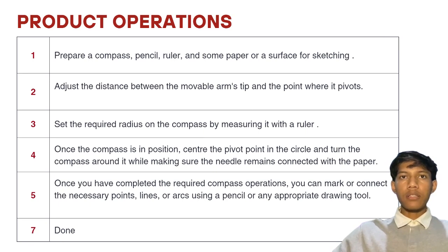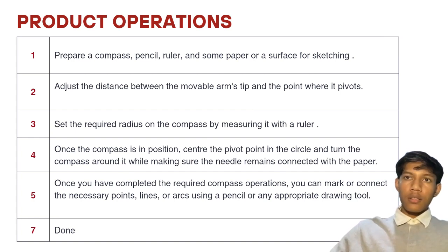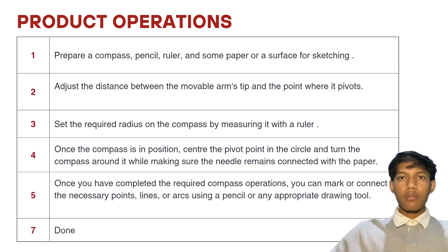6. The creation of many geometric shapes requires the use of a compass. For instance, set the compass to a specified radius and draw arcs on either side of the point to create a perpendicular line from a point on a given line. Then draw arcs that cross the earlier arcs with a wider radius. You can draw a parallel line with the aid of the connecting points.